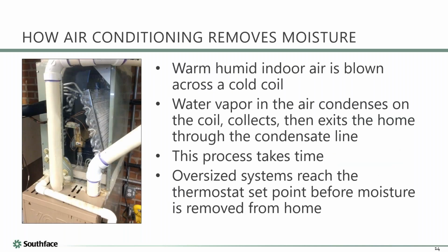And of course, in order to dehumidify air, the other big message is this coil needs to run air across it for a long time, because it takes a while for condensate to build up on the fins and drip down and collect in the pan and then drain out. This is the condensate drain right here. So it takes a while for that to happen.